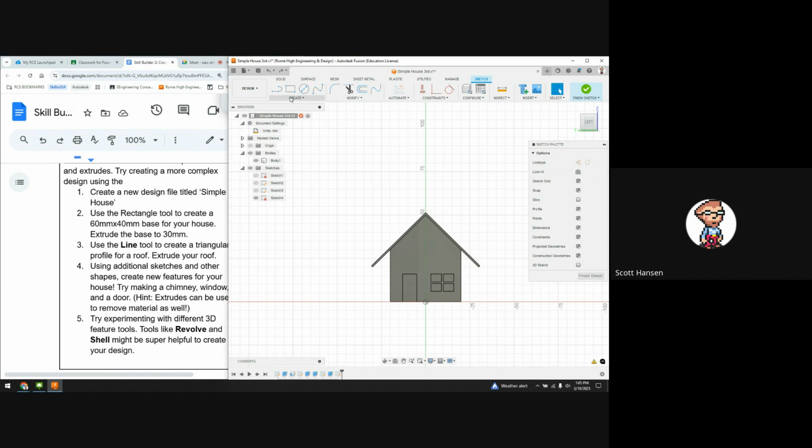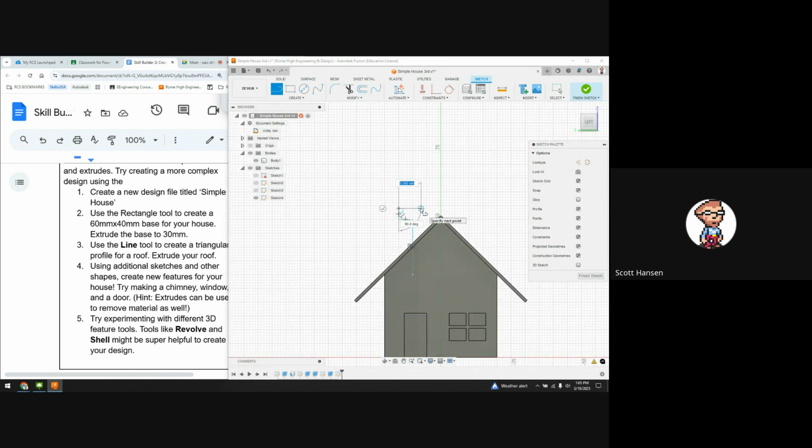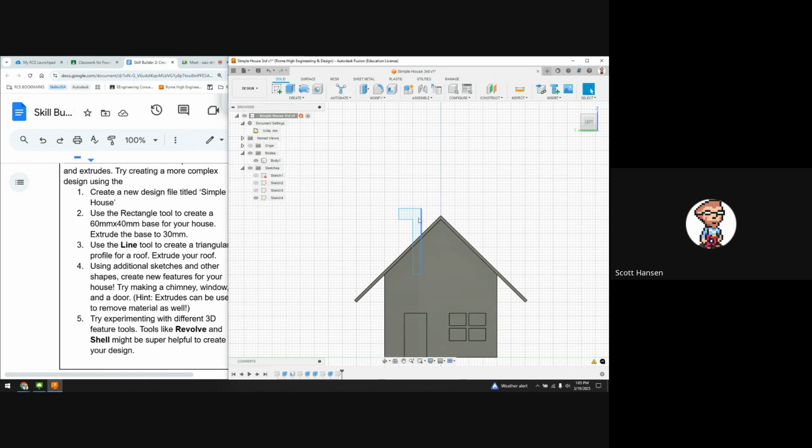And so if you're using the revolve tool, typically what you need to sketch is half of the object, half of a sketch profile. So if I want my chimney to kind of have a vertical component and maybe a top component, it may look something like this. This is not my completed chimney. This is like my chimney, if I looked at it, sort of sliced in half. Let me click Finish Sketch.